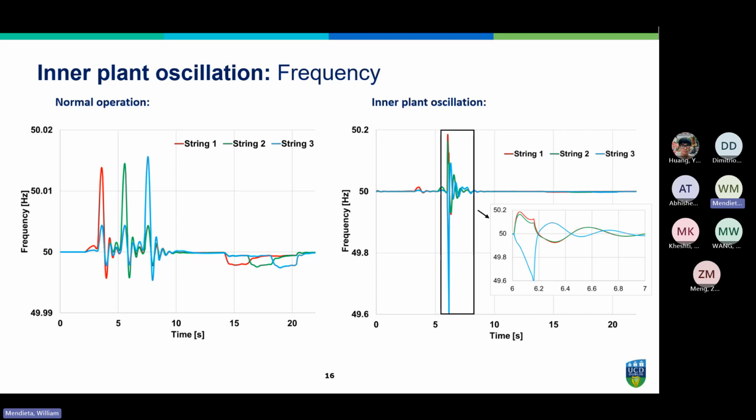In the transition from region 2 to 3, the activation of pitch control after the maximum power point tracking mode rapidly adjusts the pump torque to prevent exceeding turbine rotor nominal speed, causing a fluid pressure transient and leading to a larger frequency peak. On the other hand, in the transition from region 3 to 2, the maximum power point tracking control mode regulates the motor displacement to mitigate fluid pressure transients, resulting in a reduced frequency peak and a smoother frequency response.